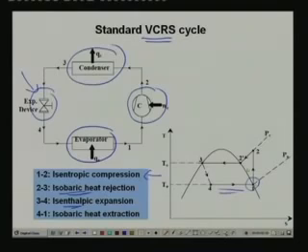But as a result of this, you find that the condensation process or the heat rejection process is isobaric but not isothermal, because during the process 2 to 2 dash the temperature is varying, whereas during the process 2 dash to 3 the temperature remains constant. That means initial heat rejection is an isobaric process but non isothermal process, whereas the rest of the process is isobaric as well as isothermal.